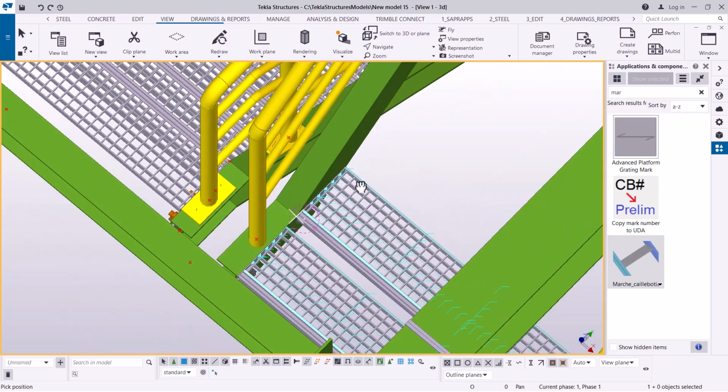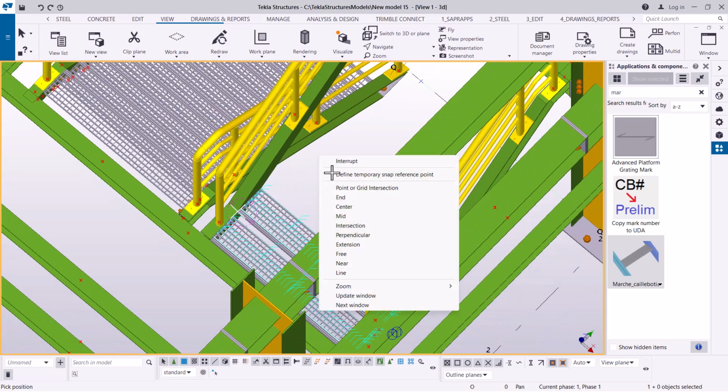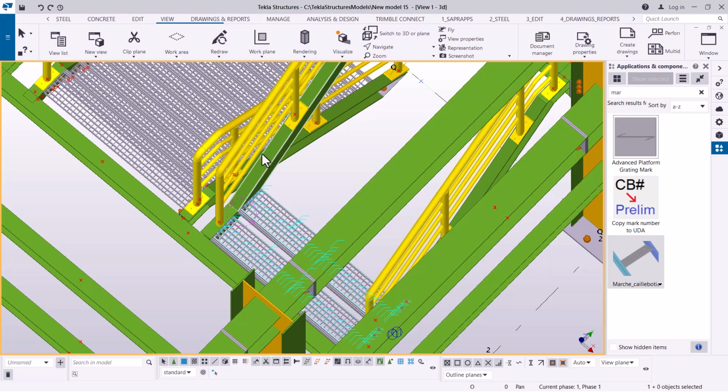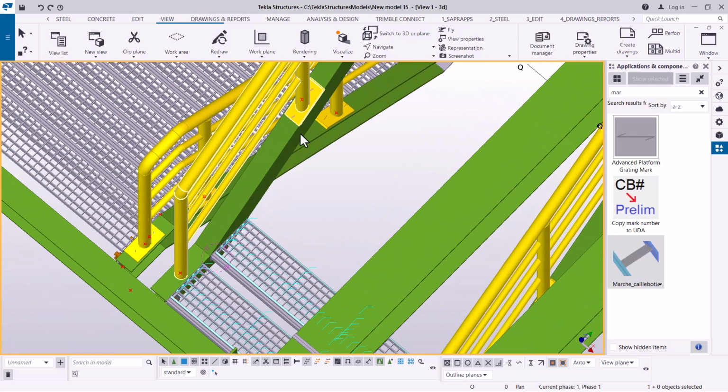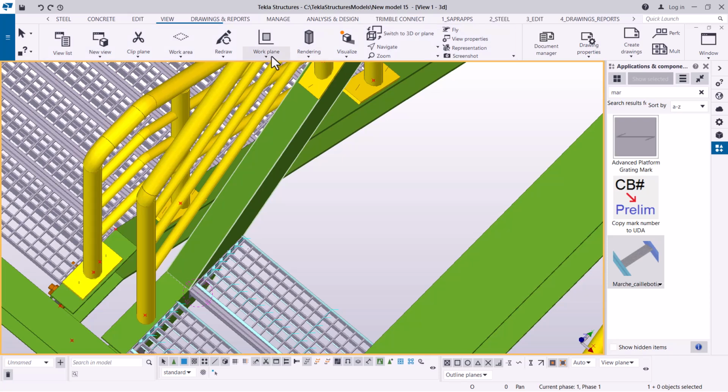You can just do that by yourself, because I had showed you on the first flight. Now we want to populate this on the upper side. So prior to that, we have to align our XYZ plane with the stringer, because the stringer is inclined going upward. So I'll come to applications here and pick on the work plane.